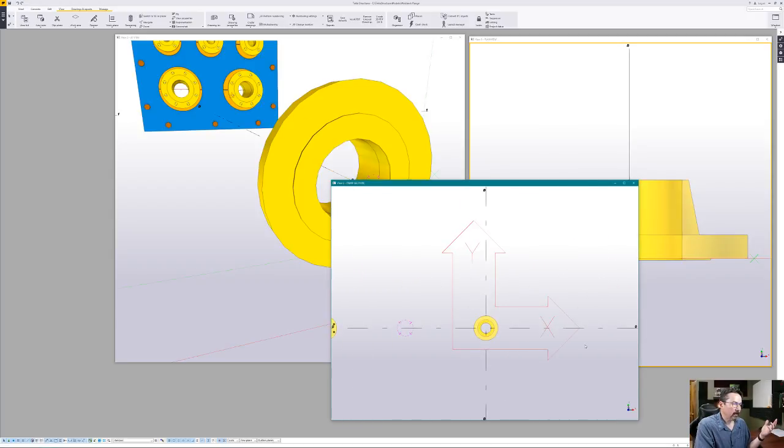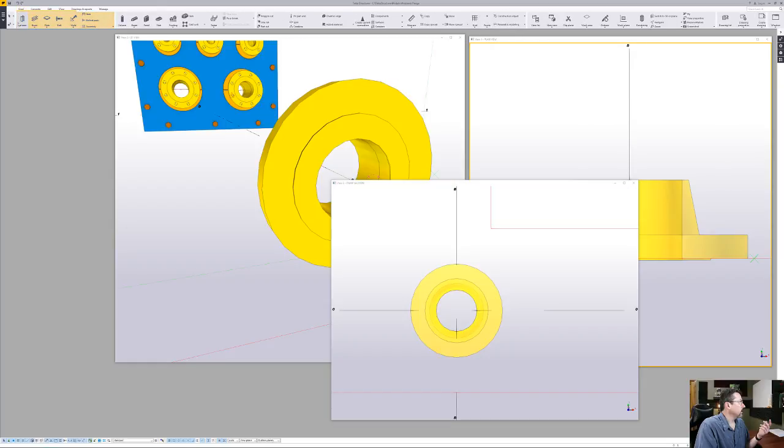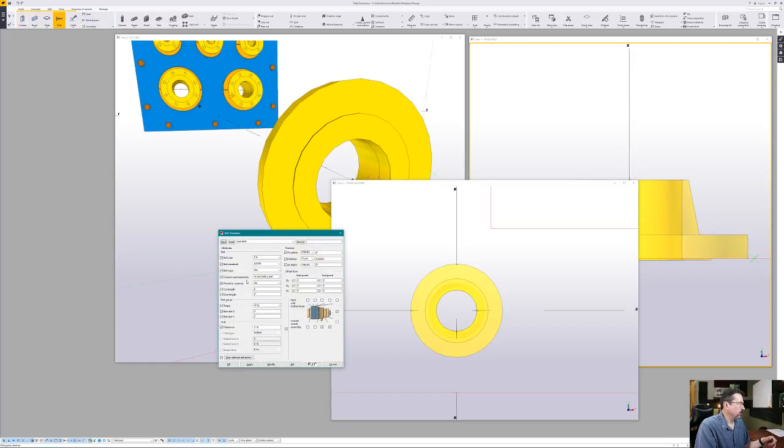You can see here that now here's my work plane with the X and the Y. I'm now working in this view. Everything is set up for this view. So now I want to put my bolts in. I have macros set up for all of that, which makes things so much easier. So now I want to do the bolts. We're going to go back to steel, select bolts, hold down the shift key and open up our bolts.